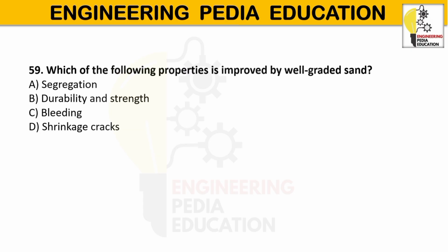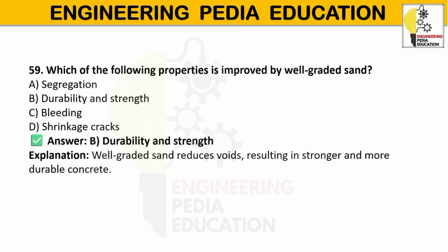Which of the following properties is improved by well graded sand? Segregation, durability and strength, bleeding, shrinkage cracks. The correct answer is durability and strength. Well graded sand reduces voids, resulting in stronger and more durable concrete. Mostly for concrete work, we use well graded sand.